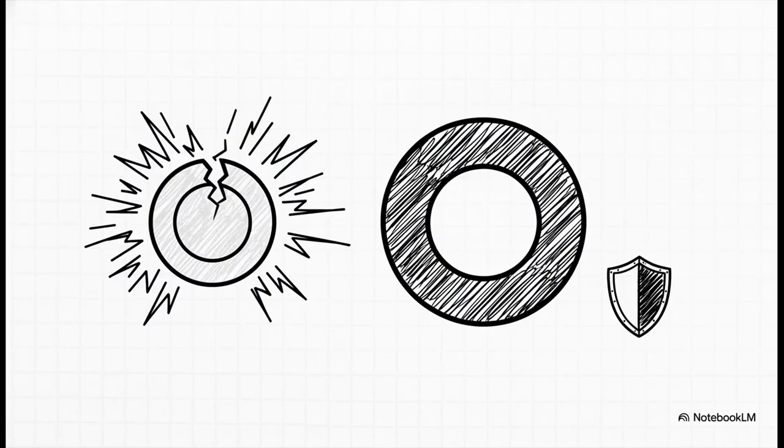Okay, listen up, because here is your ultimate fail-safe rule. This applies both for real-world engineering design and for scoring full marks on your next exam. When you get to that final Step 4, you absolutely must compute the required diameter using both the equivalent twisting moment theory and the equivalent bending moment theory. You're going to get 2 different numbers, and you must always adopt the larger of those 2 values. Think about it. If you choose the smaller diameter, the shaft might survive one type of stress, but it's going to catastrophically fail under the other. So always design for maximum safety.